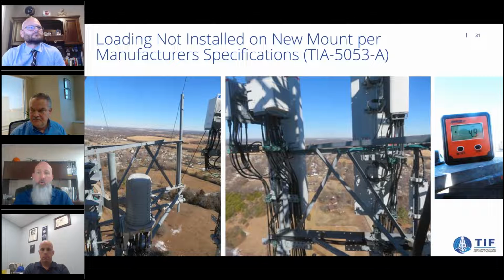And these 3 photos are why 5053A talks about unbalanced loading, because we've got 2 antennas, 3 radios, and all their RF cabling positioned in positions 1 and 2, or 4 and 3, depending on who you're talking to. And now we've got a mount that is just under 5 degrees out of plumb.